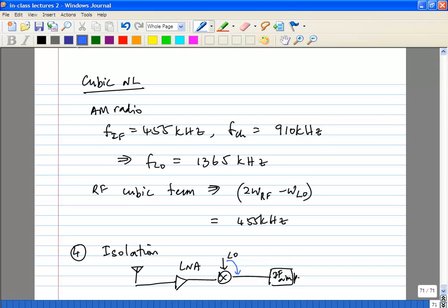You remember your RF signal is in microvolts. After the LNA, it will probably be in hundreds of microvolts, maybe millivolts. Your LO signal is usually in hundreds of millivolts, or maybe greater than a volt. So there is every chance that the LO signal coming in is much larger than your RF signal. What happens? You could saturate your IF amplifier. That is your LO to IF feed through.